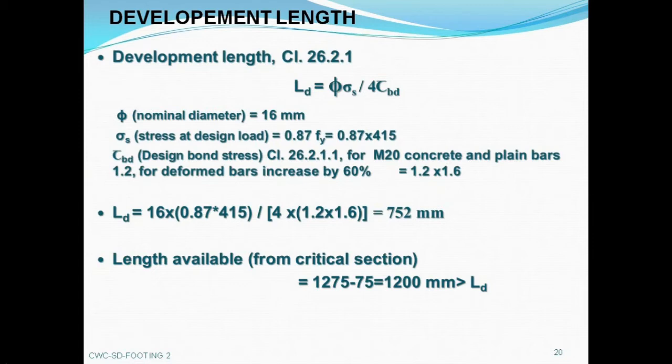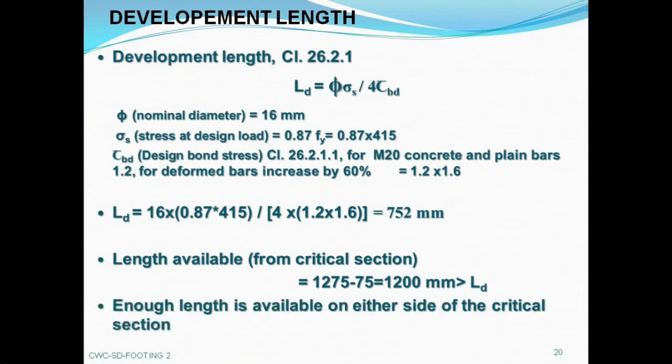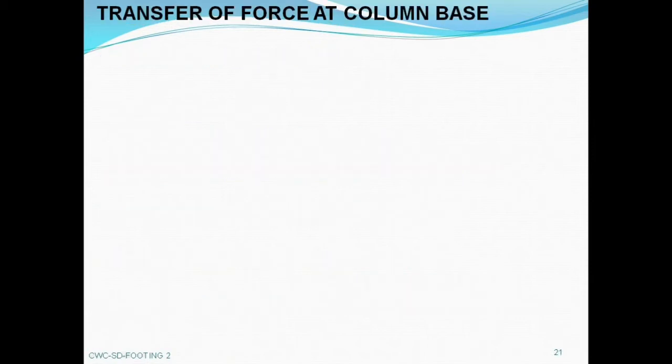So enough length is available on either side of critical section. So there is no need to provide additional provisions like bends, hooks, etc.